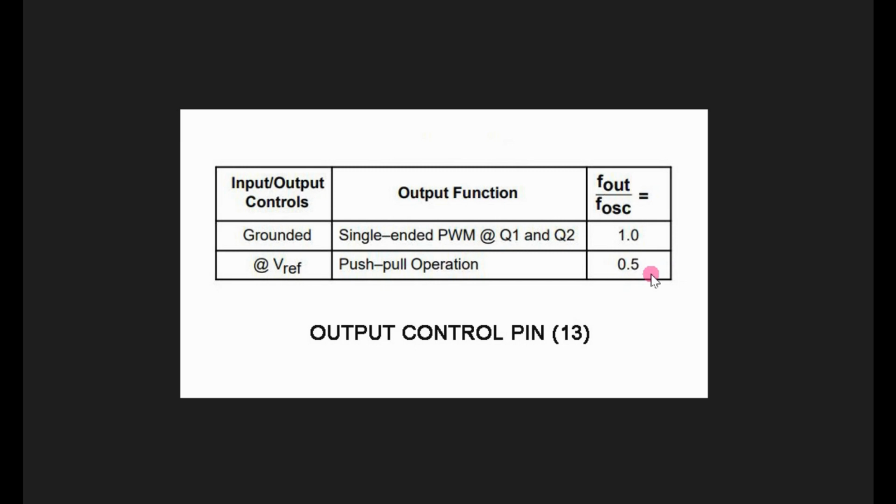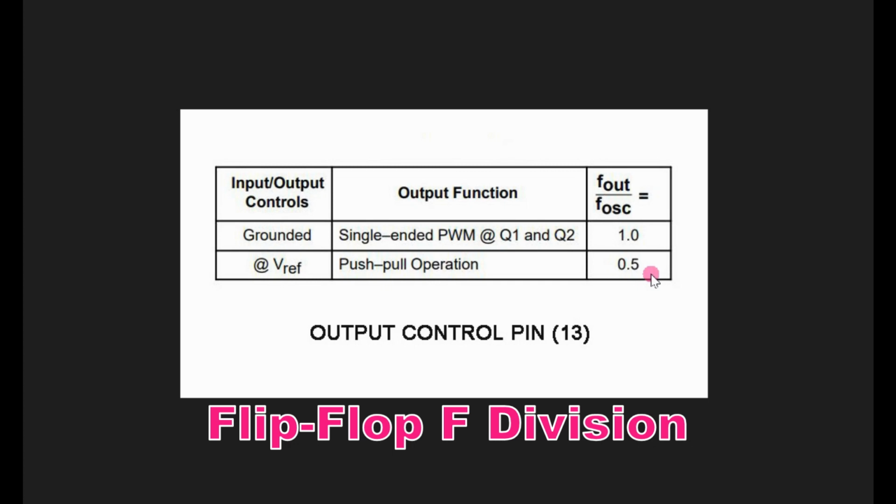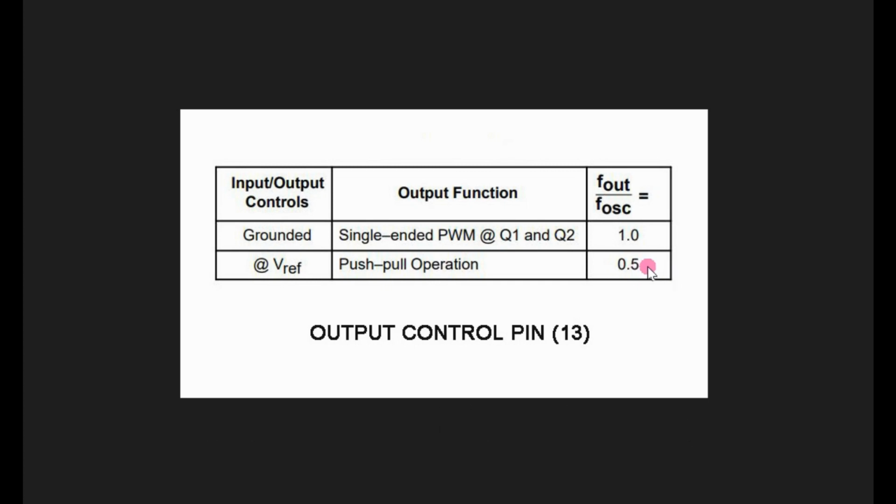However, remember, it's a flip-flop, and flip-flops divide your frequency in half. So we'll now have to raise our sawtooth wave from 60 kilohertz, where I'm running it, to 120 kilohertz to get the same effect.